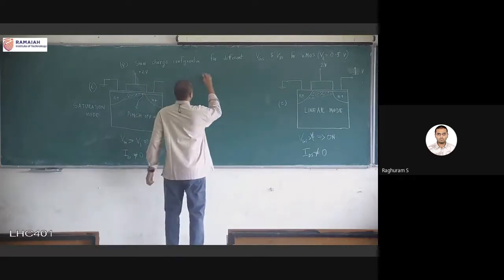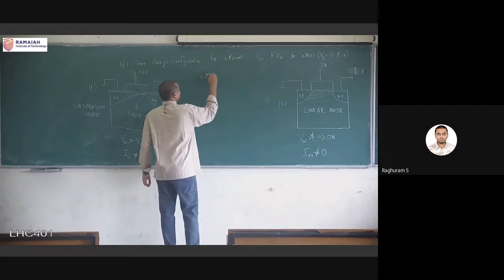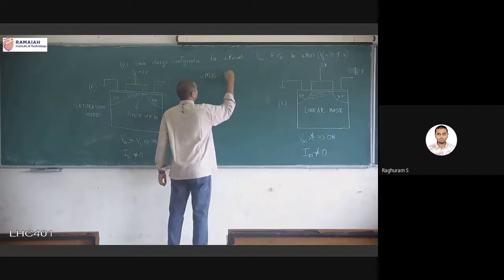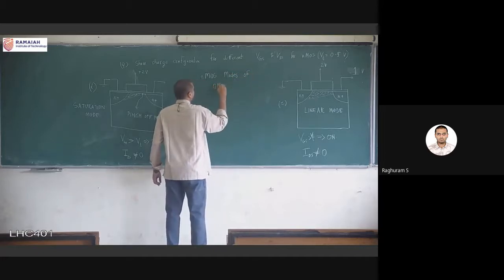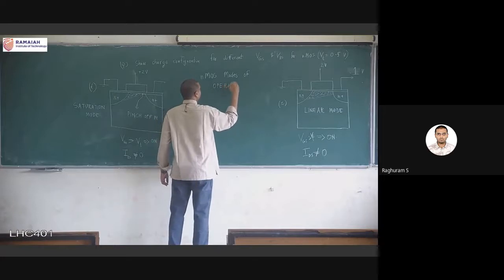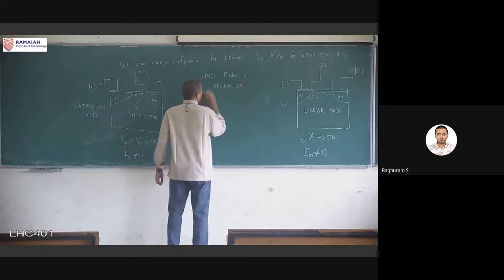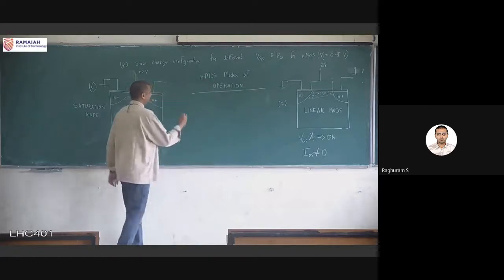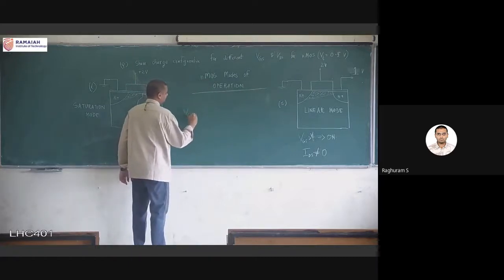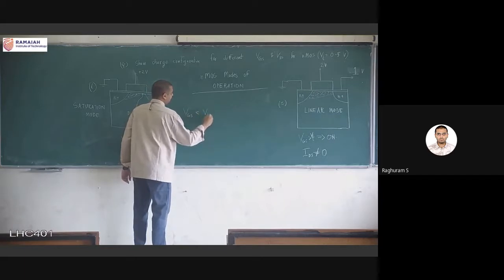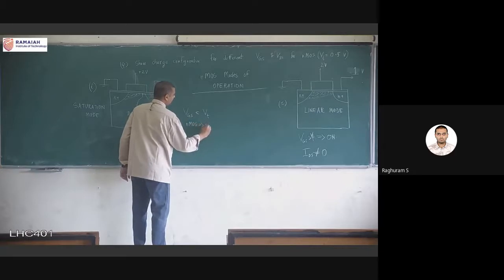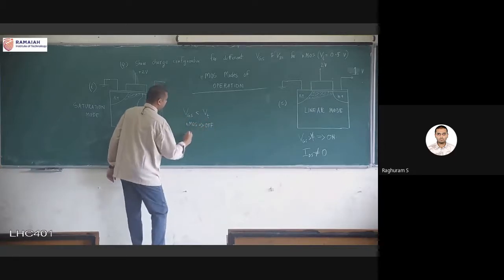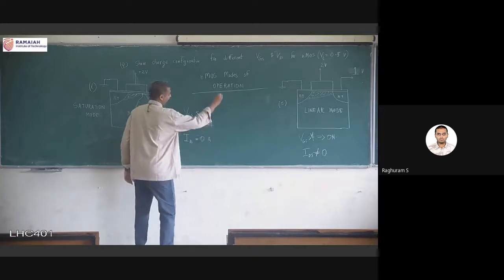So it is going to be slightly dependent on the conditions that we are listing here. We look at NMOS. On one side I will write the simplest: where VGS is lesser than VT, NMOS is off, and what is the value of the current IDS? 0 ampere, nothing to do.